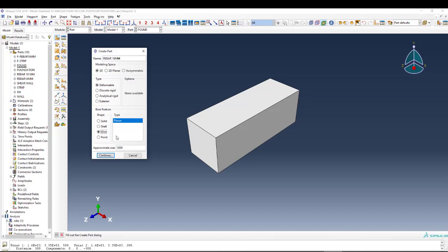If you use truss elements, you give the cross section area of the rebar. I will show you both. There are two tricky points for both elements. Sometimes you will get an error that is quite difficult to handle, but after you watch this video, you will never face that kind of problem.